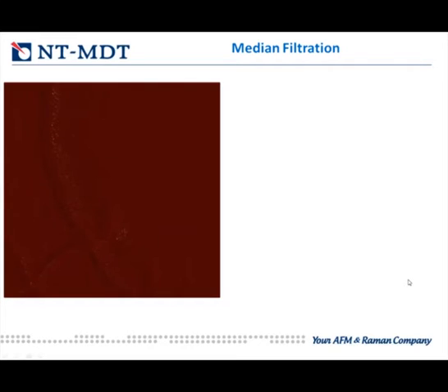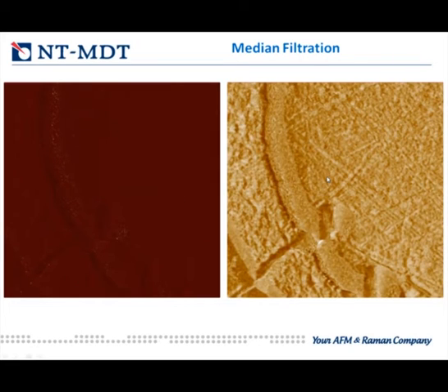As an example, there is an image where we can guess that there is something, but due to multiple spikes, positive and negative, we don't really see the details. We don't see the information, we see the noise. If we apply the median filter, that's another story. We can see all the details and the spikes are eliminated.